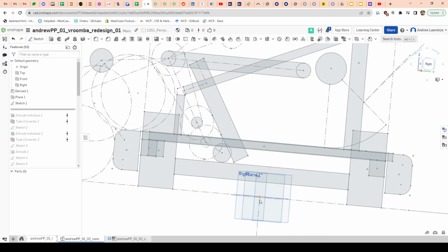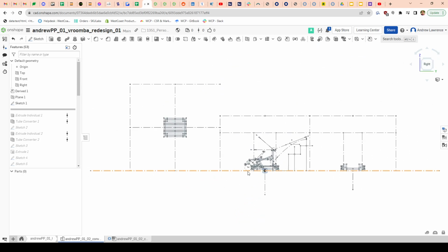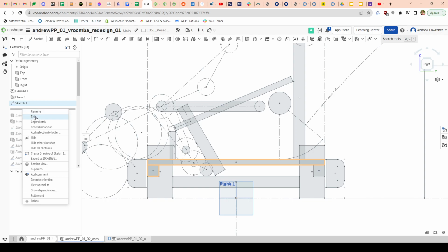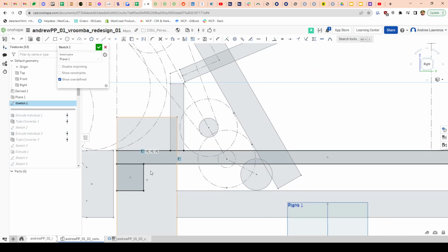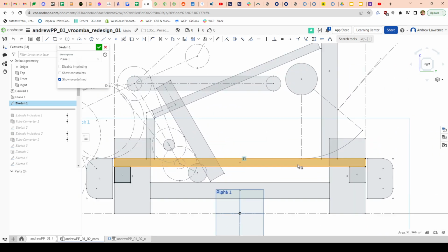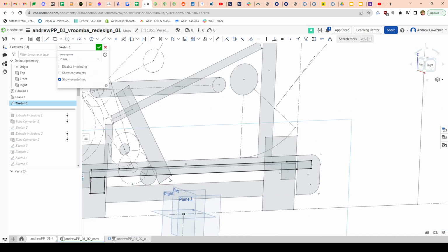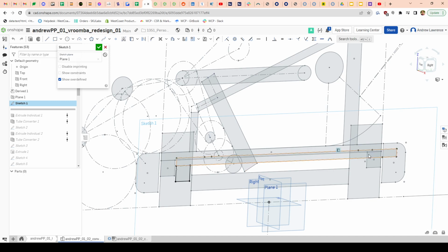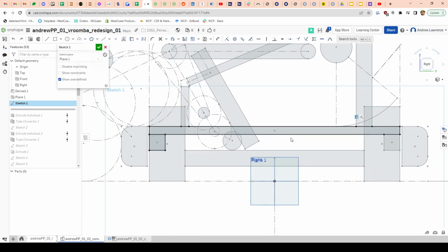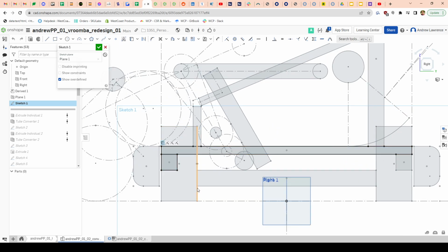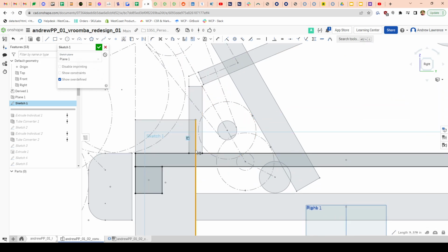And in the sketch, I actually do a couple things. So I'll open it up for you to show. In this sketch, I have selected this tube and this tube. You see no dimensions on these parts, and that is because these have been copied directly over from the original sketch by selecting a sketch contour and clicking the U key, which stands for use. Converts it over from the old sketch into the new, just as I've done with this line.